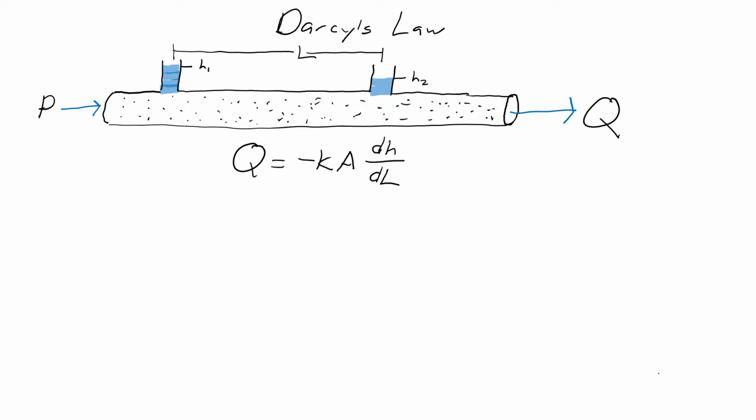So in this case, H1 is higher than H2. Pressure on the left side of the diagrams, higher than the pressure on the right. So material moves from left to right. If there's no difference in head, then there's no impetus to push the material one way or the other. If the two heads are equal, then there's going to be no flow at all. The flow just stops.